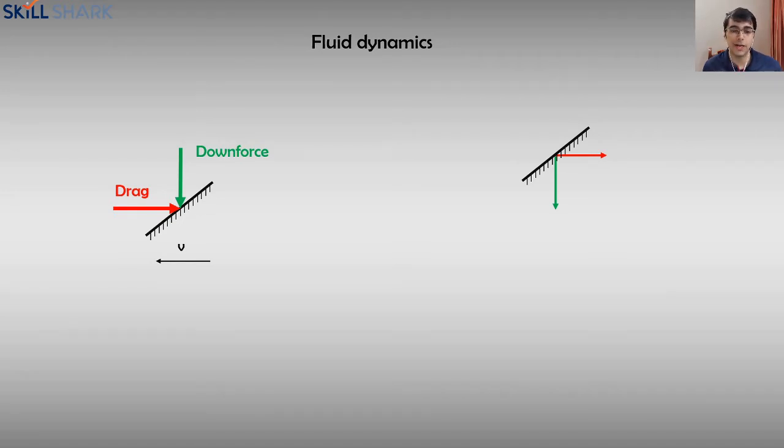So now another way to look at it is by using Bernoulli's principle, and this is more commonly used when you're looking at aerodynamics because it gives you a better understanding of how to relate pressure and velocity. It might not be easier to visualize per se. Of course, with Newton's laws, it's easier to visualize it as air particles colliding with the plate. But Bernoulli's principle gives you a better understanding of how pressure is distributed, and it helps you understand other shapes apart from just a plate.